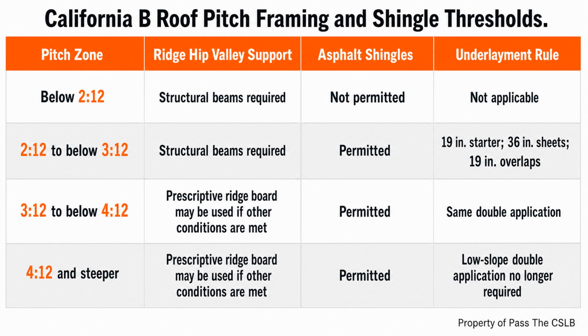Push down at the spine and the lower edges want to spread. A tie between the lower edges resists that spreading action. A solid support under the spine changes the load path by carrying the peak. The comparison is not a design method, but it makes the distinction memorable. A board lines up rafters, while a beam carries load.